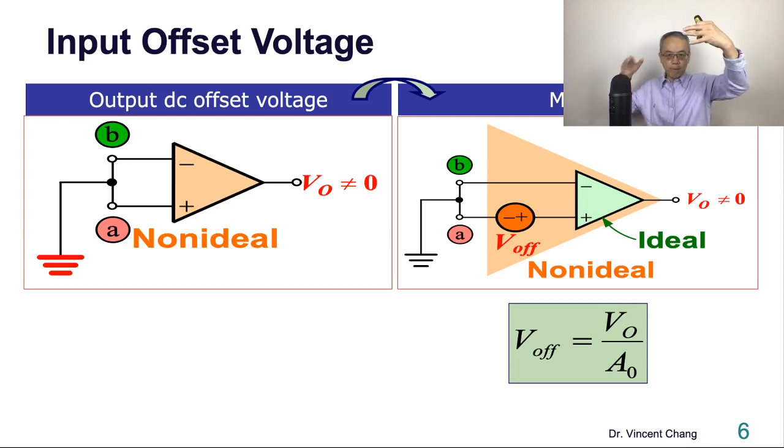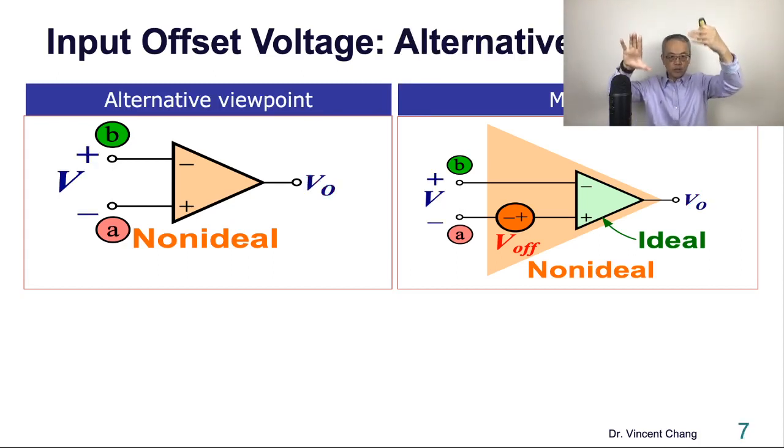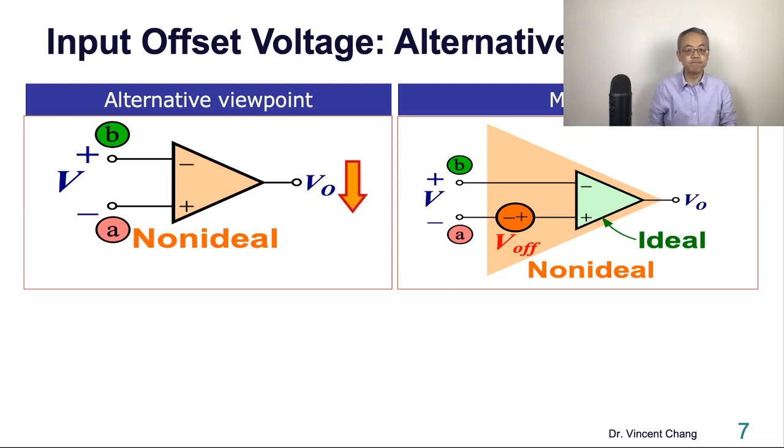So now when you apply a voltage, the output will change, right? In what direction? If you apply a voltage, look at the right-hand side, it is kind of against the internal source. The external is against the internal. The applied blue is against the internal orange. Then VO will go down.